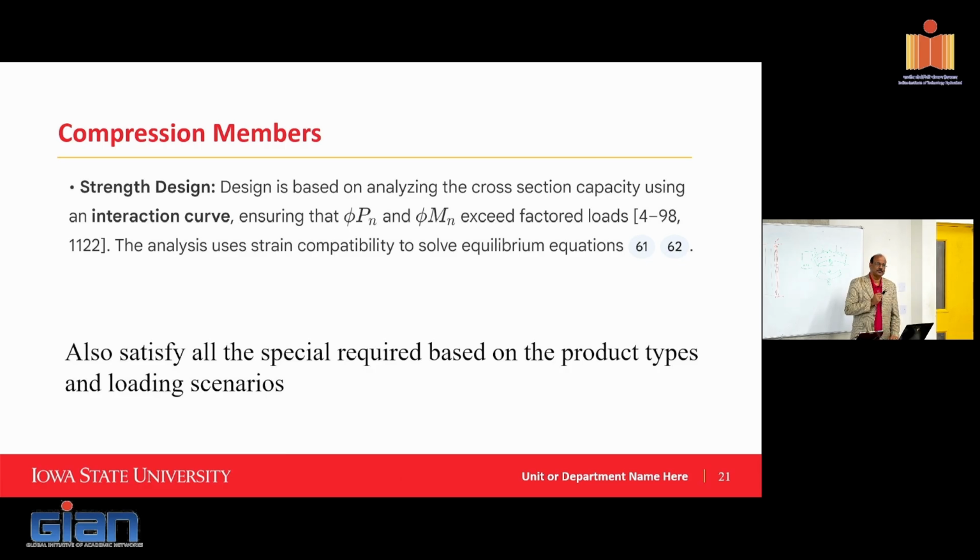One thing I want you to realize is the uniqueness of the structure is going to bring in some other challenges like this, and that's something you should pay attention to. In fact, the handbook also provides some other scenarios that you should account for. So as a designer, you should pay attention to the sequence of construction, how it's being erected, what loads the beam is seeing. So when you do actual design, you're looking at live load, dead load, snow load, and things like that. But the construction brings in additional loads that you need to pay attention to as well.